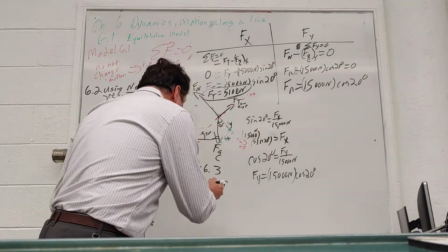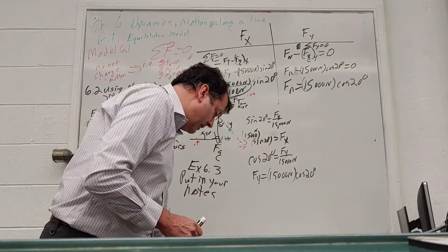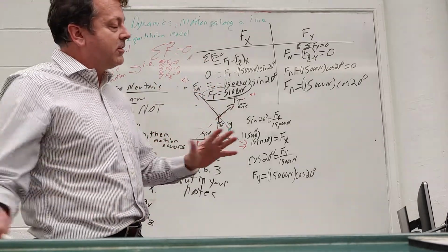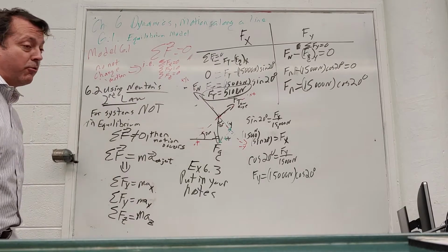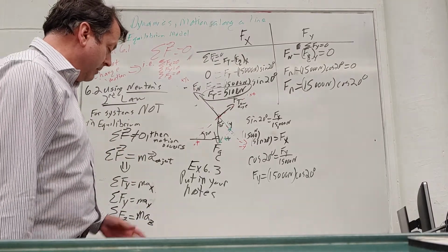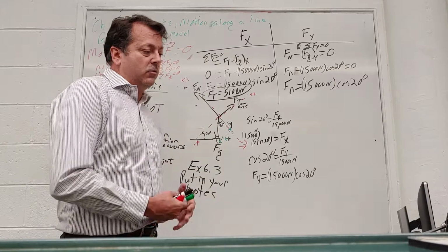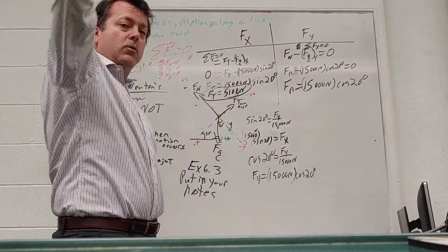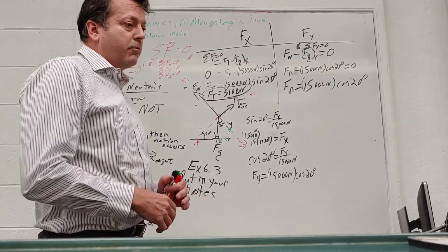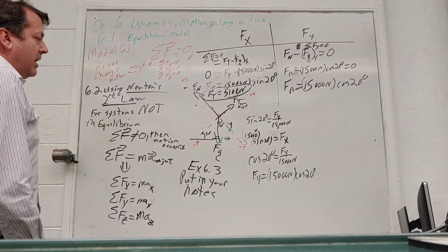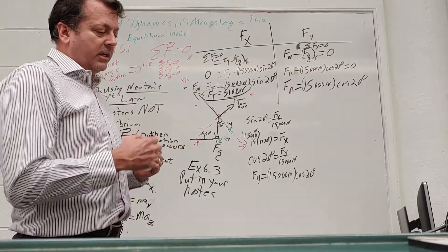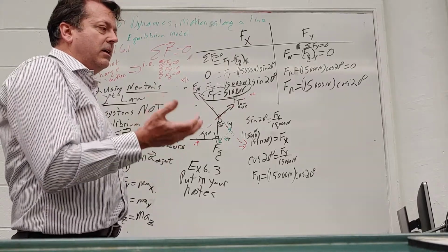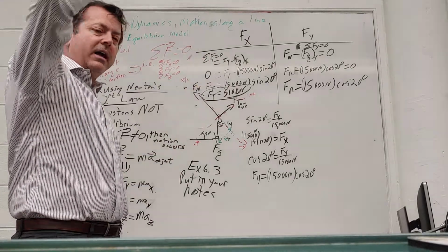I want you to have done some work with this, because in class on Friday, what we're going to do is look at the altitude of a rocket. You guys are going to be flying rockets pretty soon, and we're going to mention the project here on Friday. But a rocket, when it flies, has two phases. One is a boost phase, when the motor's pushing it, then a coast phase, when it's not. We're going to solve the problem neglecting air resistance. How high would a rocket go? Looking at how long the motor burns, and with how much force. And then, based on that, we'll look at how high it coasts up.